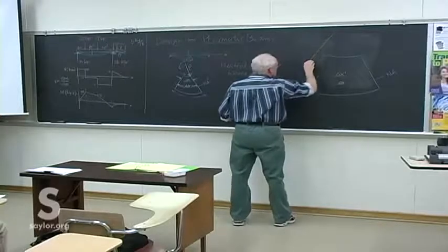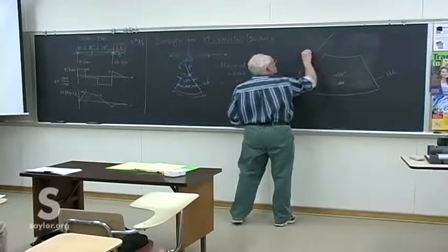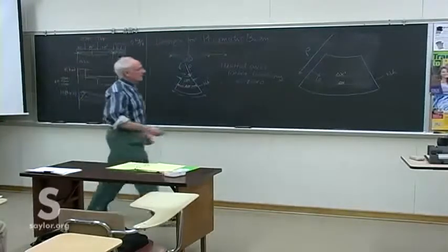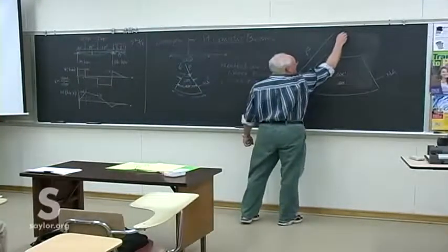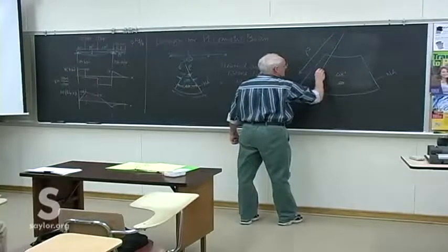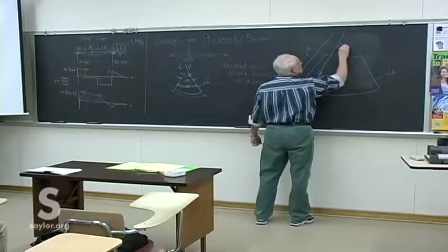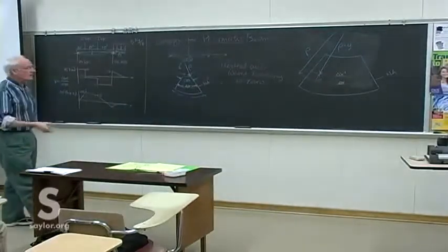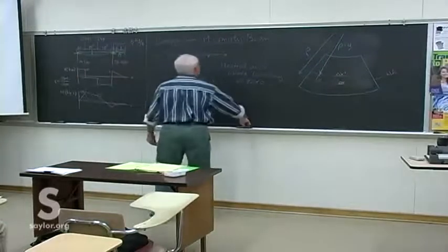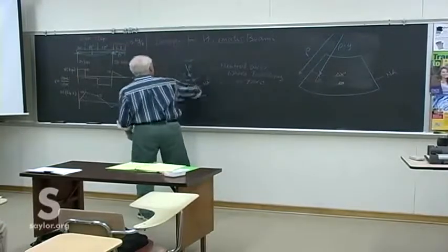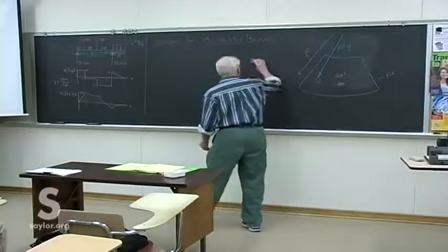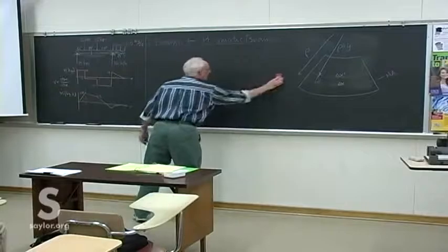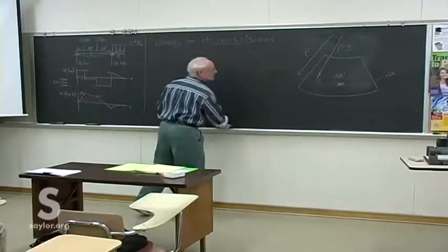All right, what else are we going to need here? The radius of curvature is rho down to the neutral axis. So down to this intermediate axis of some kind, the radius of curvature is rho minus y. And as you imagine, we're going to vary y across the entire cross-section and see where we get. So that's our geometric setup as we take a look at all parts of it as we go across.